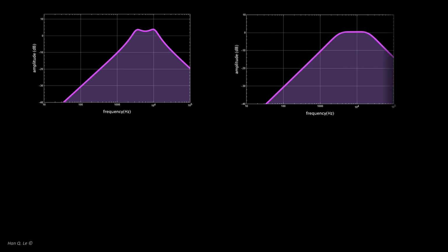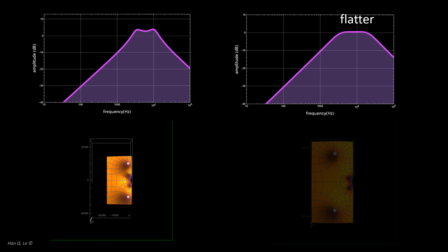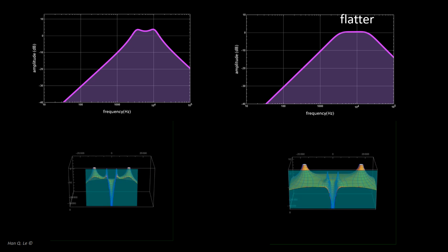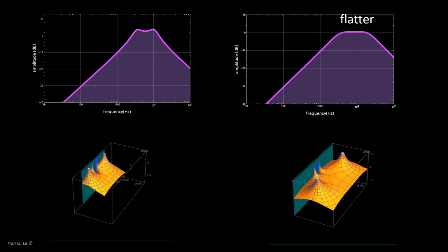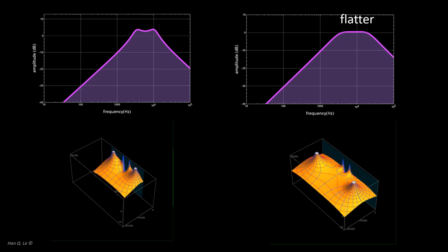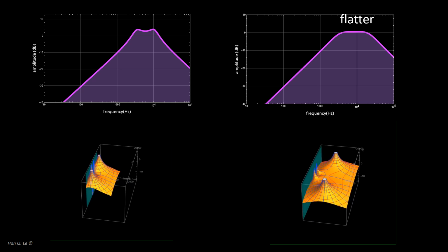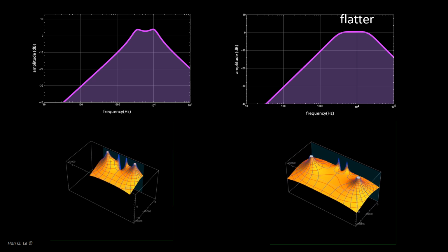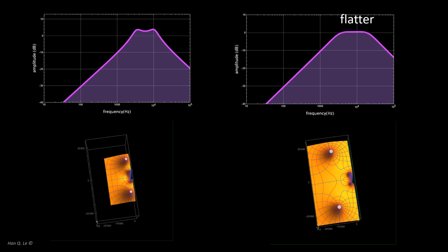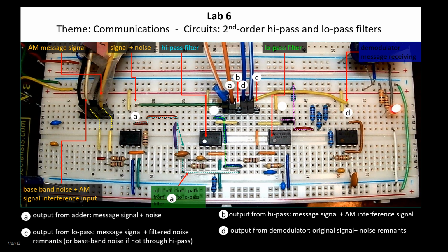As a side note, most band-pass designs are aimed for a flat response over the band, as shown in the example on the right-hand side. The different behaviors can be seen by comparing the pole positions, or the root diagrams, in the transfer functions. The poles on the right-hand side tilt more toward the real axis compared to those on the left. Hence, the behavior of the filter is closer to critical damping rather than underdamped condition, and the band top is flatter.